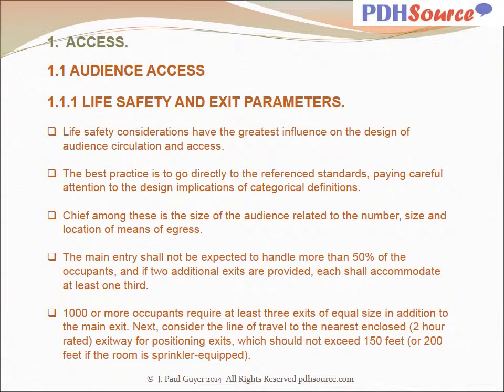With regard to audience access, life safety, and exit parameters, life safety considerations have the greatest influence on the design of audience circulation and access. The best practice is to go directly to the referenced standards, paying careful attention to the design implications of categorical definitions. Chief among these is the size of the audience related to the number, size, and location of means of